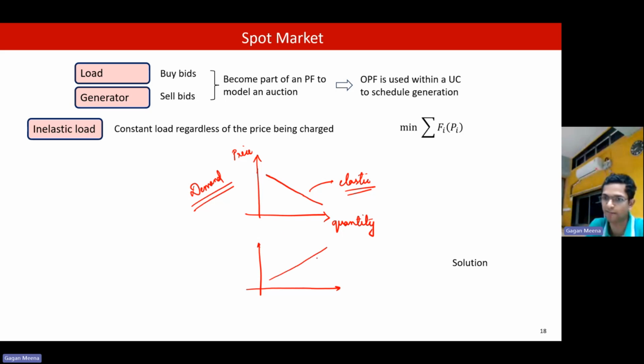And as the capacity is utilized and the older units with a higher incremental cost are added, the overall incremental cost of production increases. That is where the supplier or the generator has an incremental cost and the demand has a decremental cost. So this is a generator. And in between, you can see at some point the two can intersect each other, and that point is the point where the market is cleared.